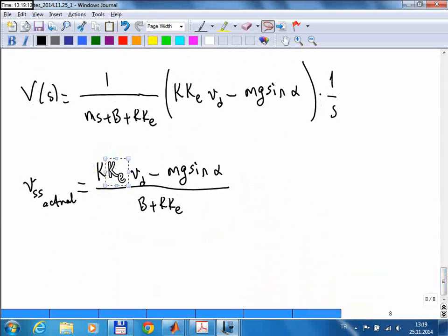So that means even for finite values, if it's large enough, you can make sure that the effect of inclination or the effect of the error in your engine can be made very, very small. And this is with a constant controller k. And if you use a more advanced controller with some transfer function, you can make it even better. Okay? So hopefully you will see all of this in MATLAB when doing these simulations.